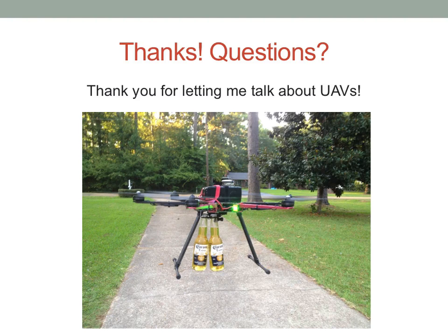Someone have another question? No. Yeah. Does it have terrain following capabilities? Because if you're going to try flying at DVH, you got hilly terrain. Right. So for that application, you wouldn't need to fly at DVH height. You would just need to fly in sight of the bottom and the top of the tree. So you could be up or down as long as it's within the field of view of the camera. But terrain following is important if you're doing an overflight and you want to maintain a consistent ground resolution, right? Because if you're flying at a fixed elevation, but you're on the side of a hill, you're going to have lower resolution here or higher resolution here.